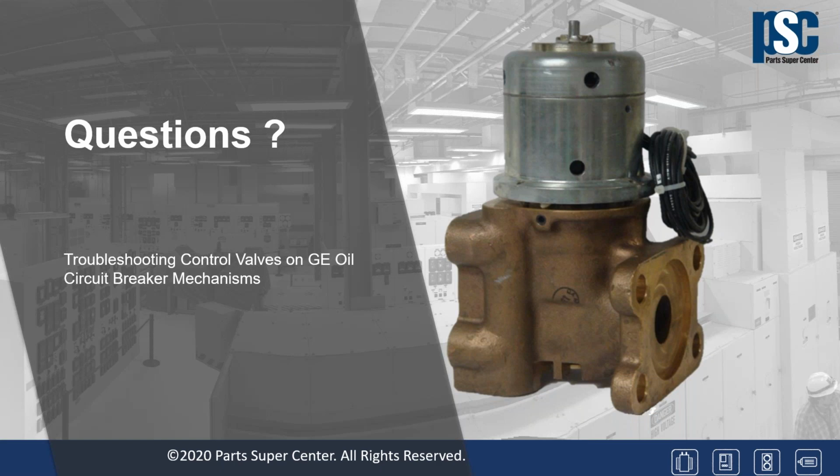We have a coining fixture where we take the entire valve coil assembly, put it in a fixture, and then we have a hydraulic press that will match and coin the pilot armature ball to the pilot armature seat. So we haven't had much success in the field doing that, and we would recommend that you replace that whole coil assembly, that top assembly, including the pilot armature seat and pilot armature, if you cannot get it to not leak, and if you've established that you have the correct pilot armature spring bias.